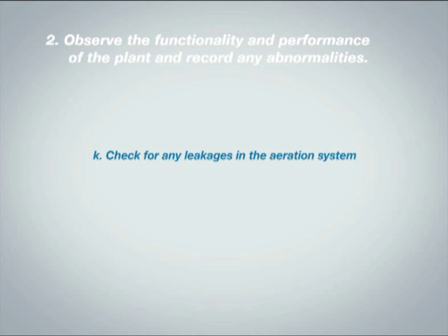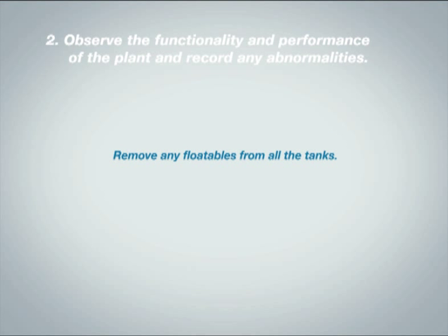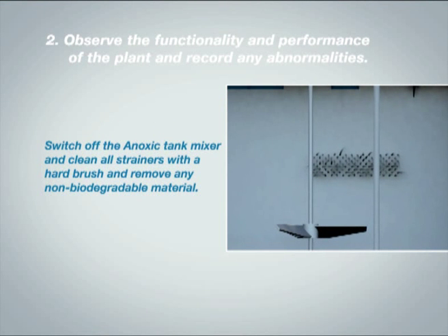K. Check for any leakages in the aeration system. L. Check for any leakages in the chemical dosing lines. Remove any floatables from all the tanks. Switch off the anoxic tank mixer and clean all strainers with a hard brush and remove any non-biodegradable material.